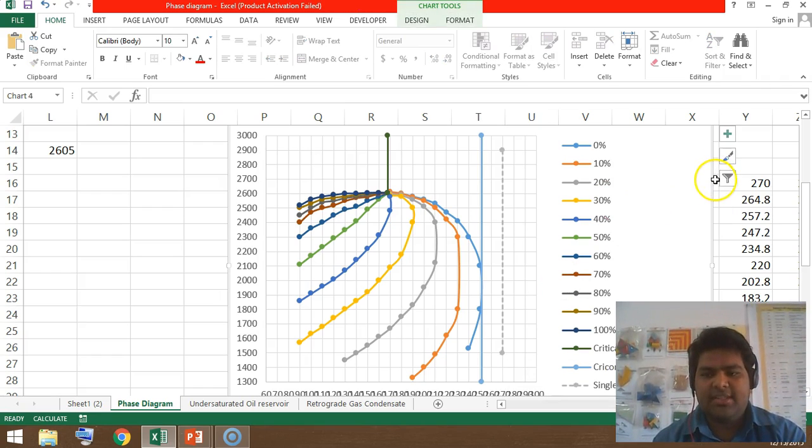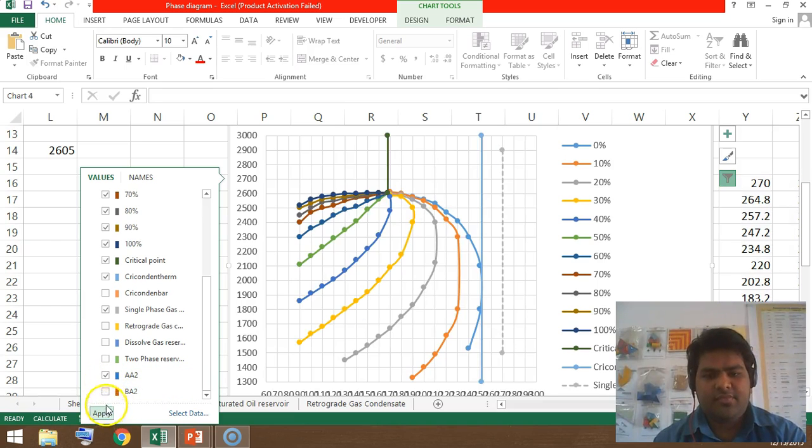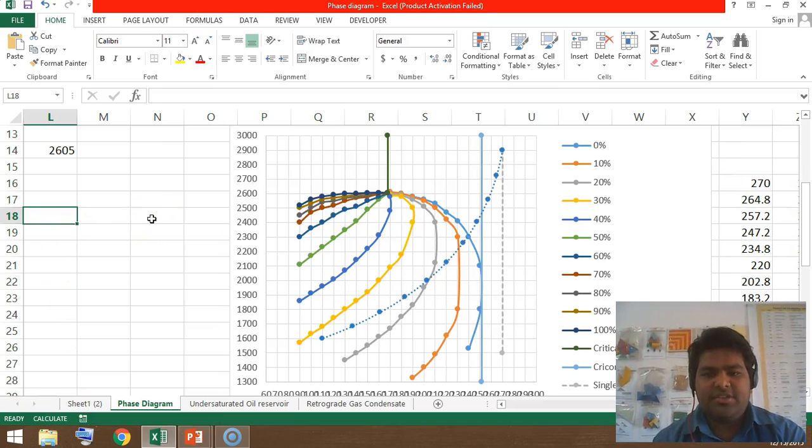But on the surface, now let's look at the fluid which we will achieve at the surface. While traveling from the bottom of the well to the surface equipment, the temperature and pressure both drop. So this path, let's call it A and this point A2. This path will be the path followed by the produced fluid. As it moves along the wellbore, the pressure and temperature both drop, so it will follow this curved path. Finally, as you can see, this point A2 is inside the two-phase region. So the fluid which we will receive on the surface will be partially liquid and partially gas.